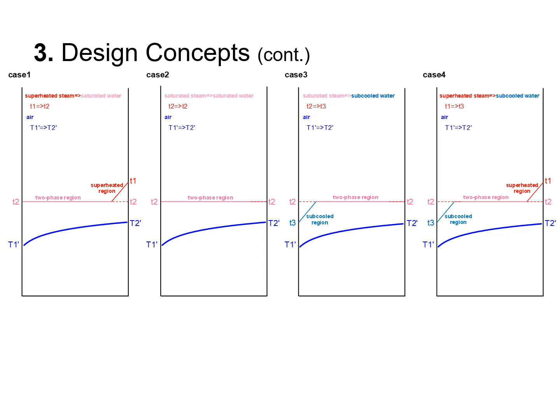The picture shows 4 different ways that heat can be exchanged in an air-cooled heat exchanger or steam core air heater. The steam that goes into the heat exchanger is either superheated or in a saturated state. After the steam gives off heat to the air, it condenses into either subcooled water or saturated water.